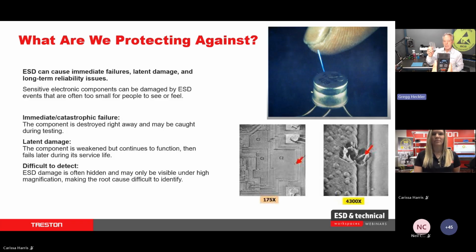You cannot ground insulators. So one of the goals of the workstation, we'll talk a little bit more, is whatever things that you have on it that are conductive, whether it's a conductive bin sitting up on one of your rails, a tote box like this, the bag, the board sitting on the thing, we want to keep all those conductors at equal potential.